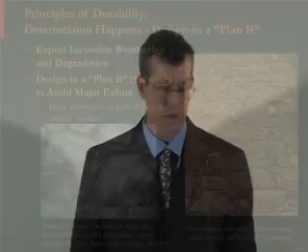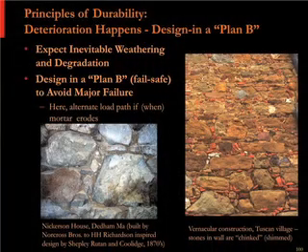Right down the road, here's an old rickety wood barn, must be 75, 100 years old. That wood is definitely getting more wet than the wood on this house, which has the synthetic stucco over it. But it's much more able to dry out. So although that wood is split and cracked and that barn looks like it might blow over with a good breeze, the wood wasn't rotted. And the reason there is all about drying potential, built in a lot of forgiveness.